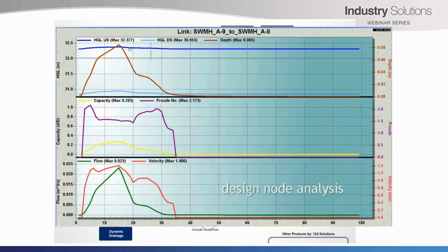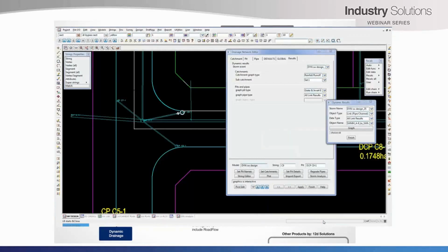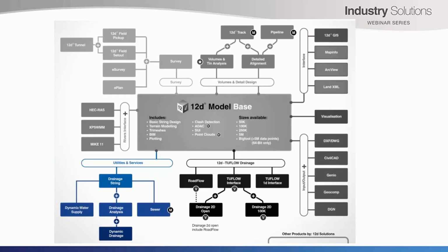The inclusion of the hydrograph methodology allows for the design of basins such as dry retarding, wet detention, and interconnected basins to be properly supported. Hydrograph methods already implemented within the software are ILSAX, SWIM, and SCS. Hydrological components such as snowmelt, groundwater, and exfiltration can also be modelled.